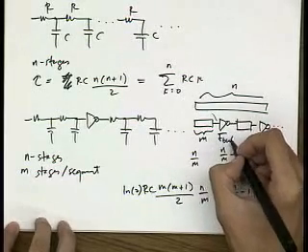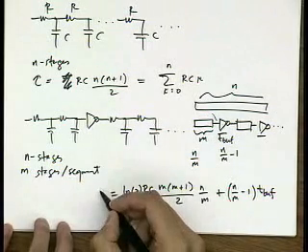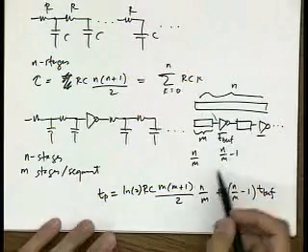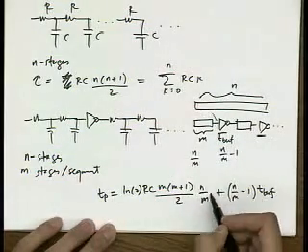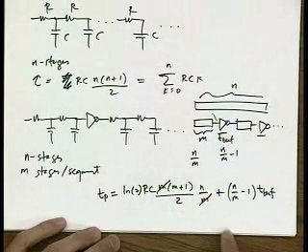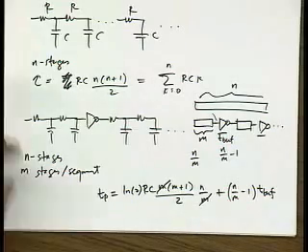This gives me my propagation delay. And notice what this does: the m cancels out, I take away the quadratic dependence on n, and it gets down to linear dependence on n. So I just need to break it up into several components. Any questions on this?